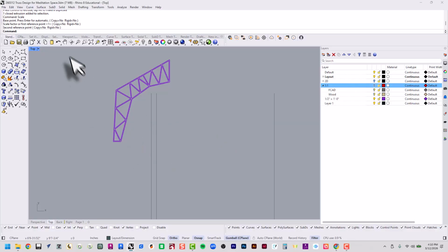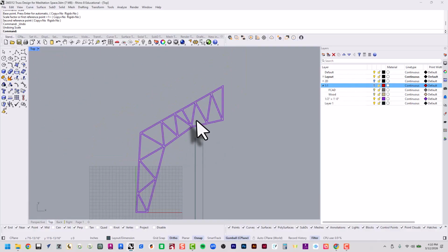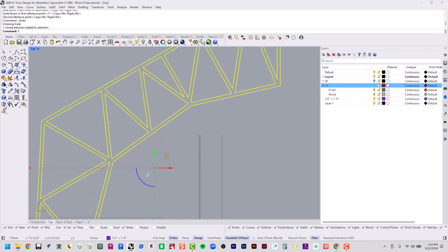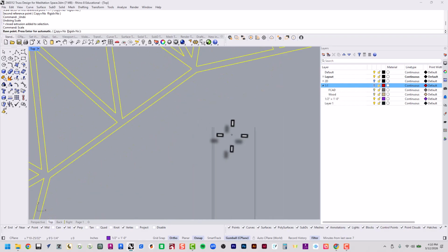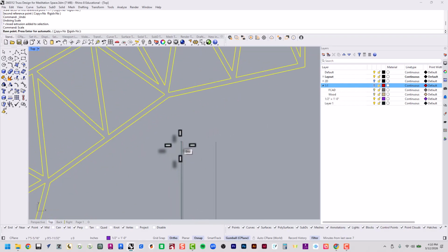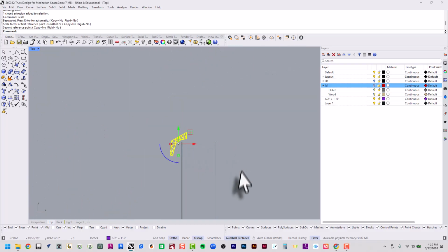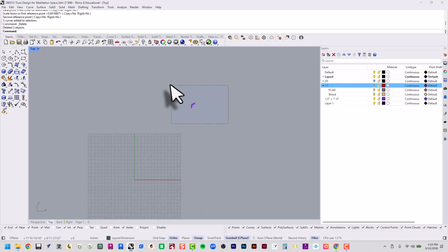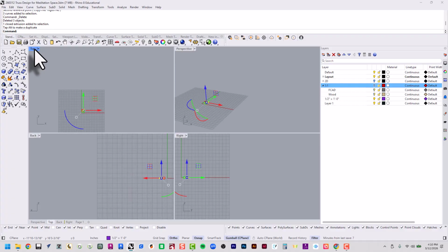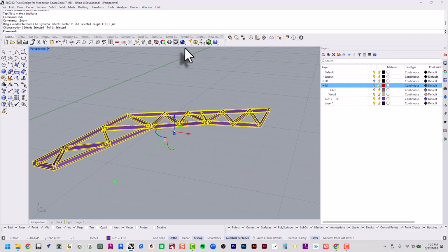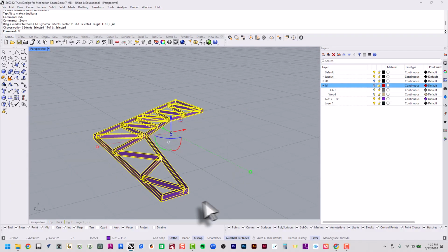Selected it, scale, enter. Basically what I'm saying is everything that's 12 inches long, make it equal to half an inch instead. And voila, poof, perfectly scaled. So let's hit delete. Let's scooch this on over. Let's go to our perspective view so I can see it a little bit better. Let's move it from here to the origin, ZSA,